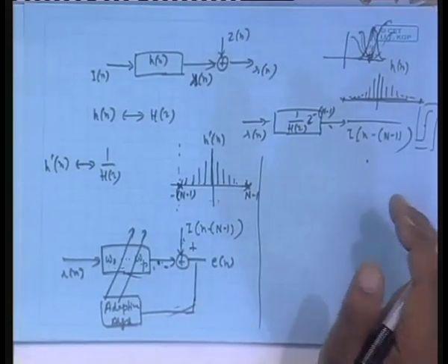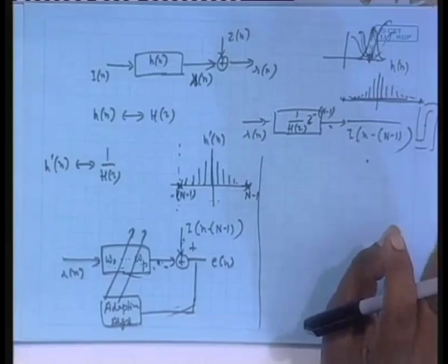In the decision process itself, some effect of noise can go, because say around 1 volt you have got a slot, you have got a band, 1.5 on the top and 0.5 on the bottom. So, within that band anything falling will be equated to 1. So, originally that receive value would have been 1, but because of noise it is 1.15, 1.3, or 0.8, 0.9, all will be quantized to the correct value only, isn't it? So, by the quantization process itself much of the noise will go, that is what we hope. We could have been living happily with it.